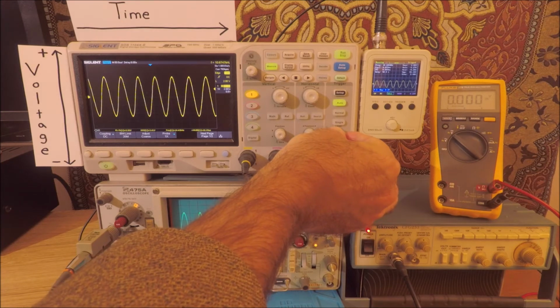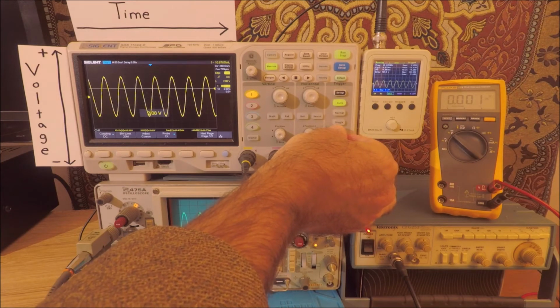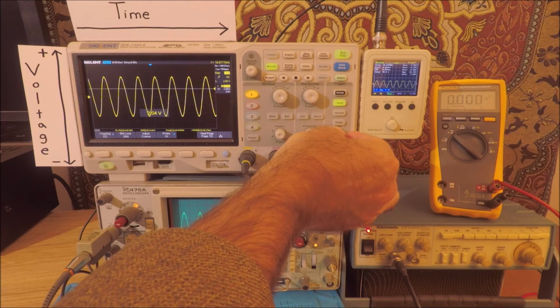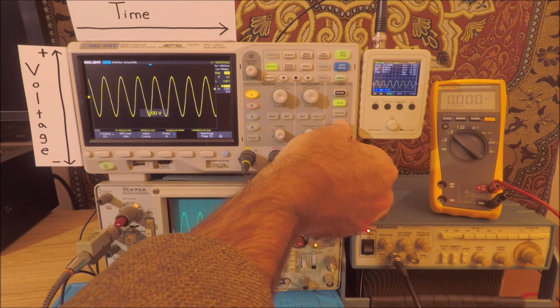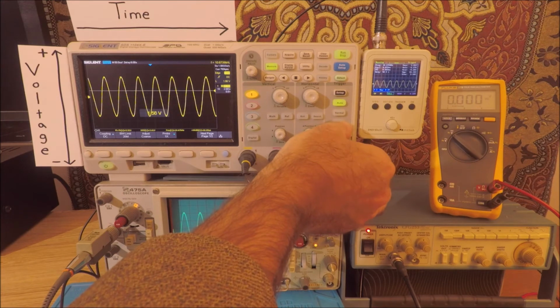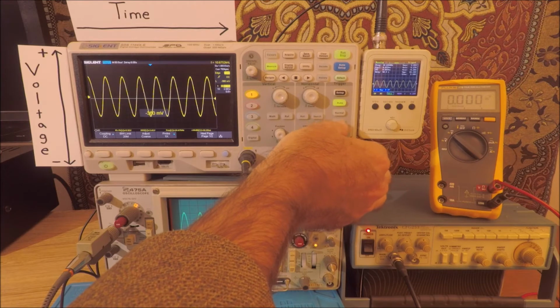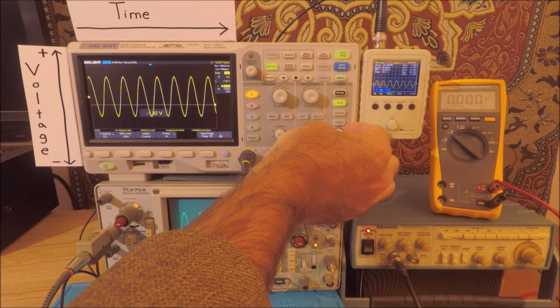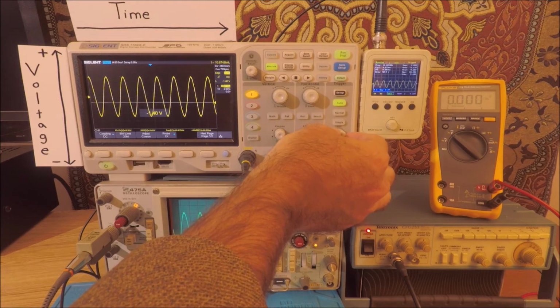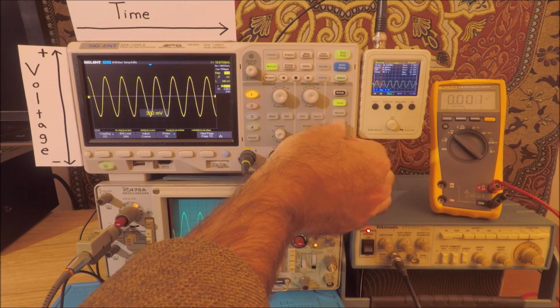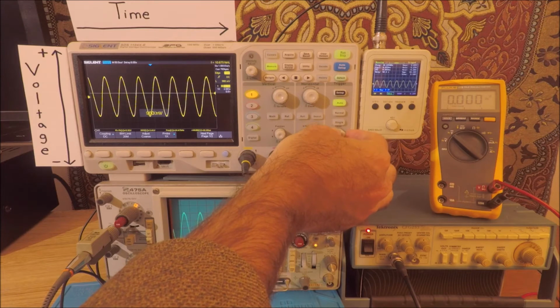As I move the trigger control up or down, you'll see a horizontal threshold move. Right now, I can set it to 2 volts. And notice that if I start to reduce it from that, you'll see the entire waveform shift to the right as I'm reducing it. And now as I increase that threshold control, you can see the threshold is moving up and the waveform is sliding to the left.